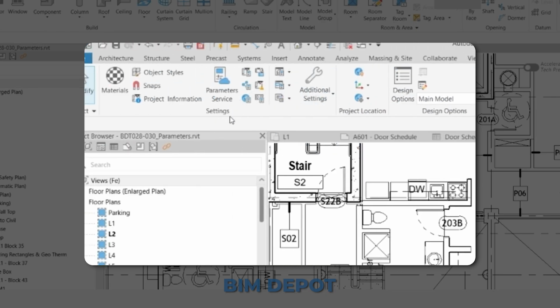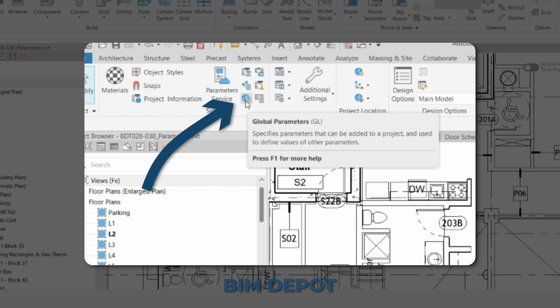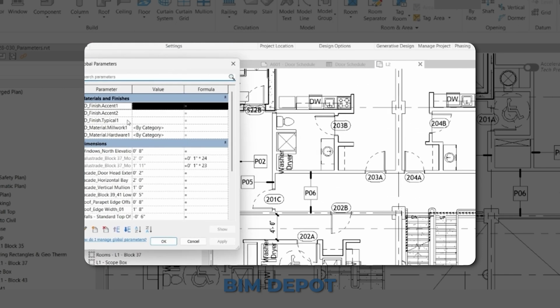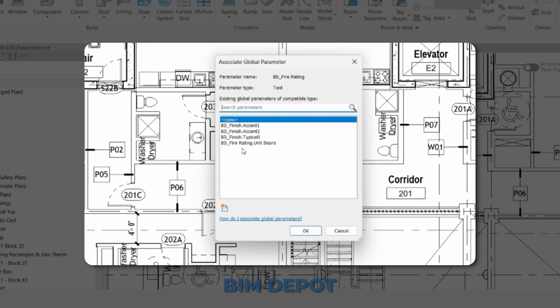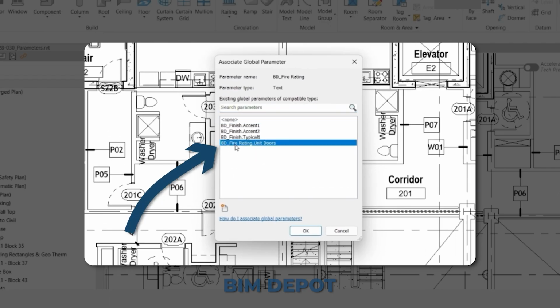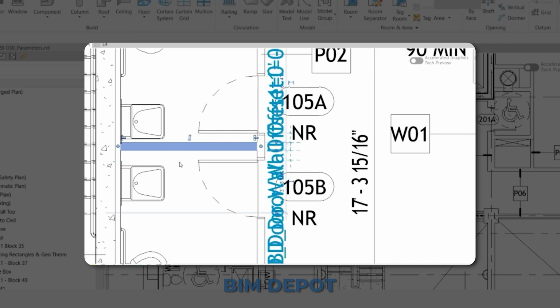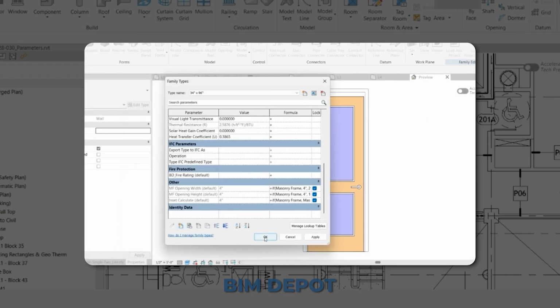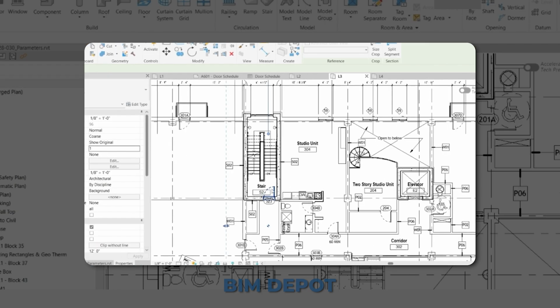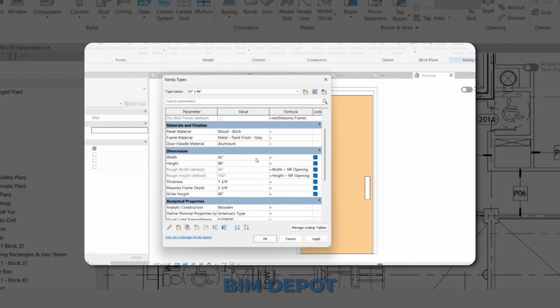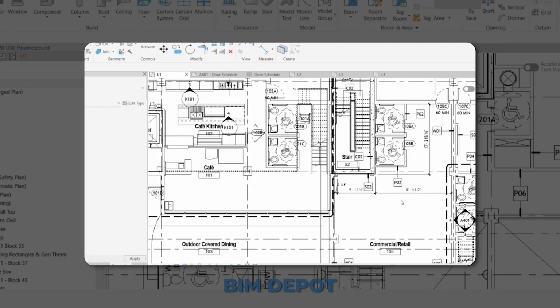A global parameter in Revit is a project-specific variable that controls multiple dimensions or instance parameters from a single location. They enable parametric design by linking elements, driving consistent geometric or spacing, and supporting formulas or reporting values for schedules. They live within the project file and are not reusable like shared parameters. Global parameters are the ultimate quality assurance tool.